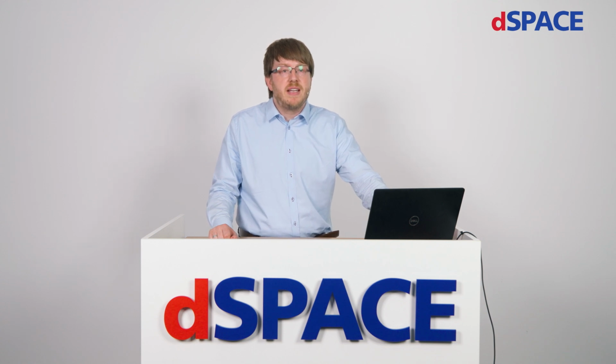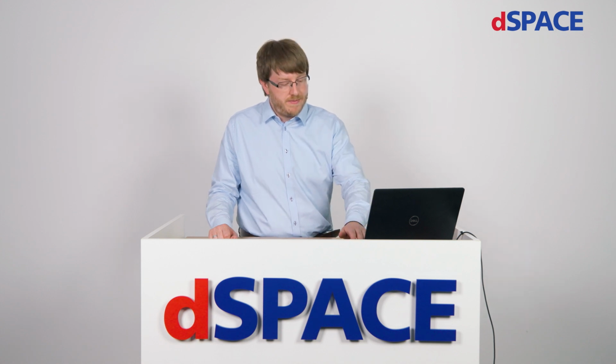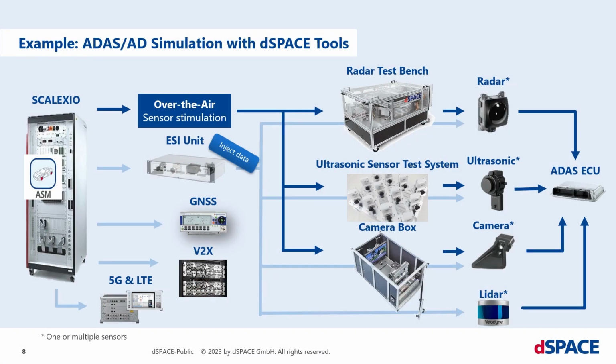I already said that all of these methods complement each other, but they can also be directly combined. This is an example for a comprehensive ADAS AD simulation using different tools from dSPACE. There are different over-the-air test solutions for radar, camera and ultrasonic, as well as the possibility to inject data with the EASY unit.